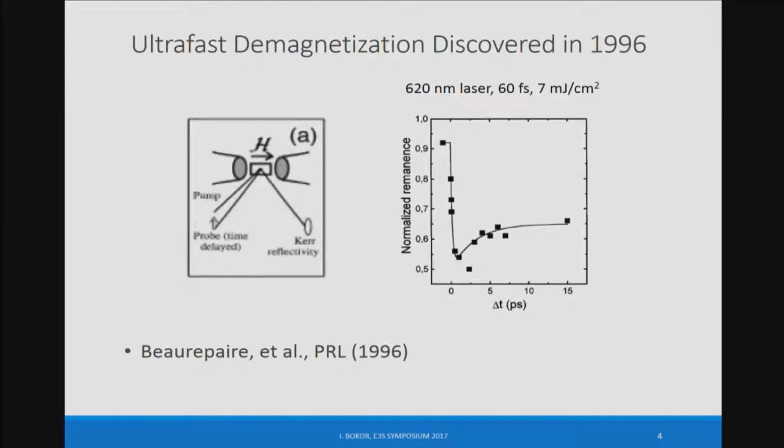So the physics of magnetic switching that we just heard about has to do with the fact that there's a characteristic frequency associated with making a magnetic layer go from up to down or left to right. And that frequency is called the ferromagnetic resonance frequency or the precession frequency. Dr. Prévenu spoke about switching relative to the period of that oscillation. Typically the oscillation frequency is in the neighborhood of 10 to 20 gigahertz.